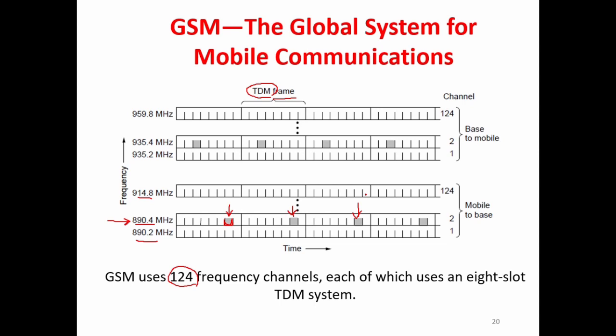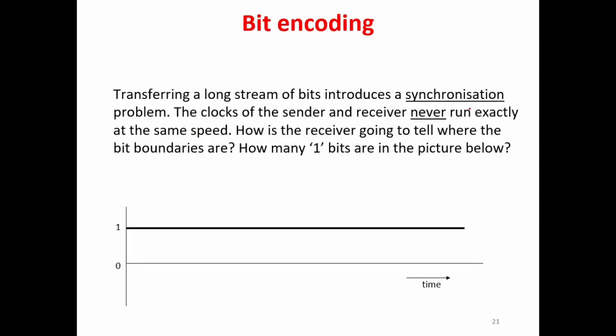But this happens actually in a very, very short time, so the receiver doesn't realize this is happening. So this sampling time would be very short. The procedure is like this. Here, for instance, again, automatically for this different time slot, the voice message is transferred from sender to receiver. And this is the application of TDM, working with time instead of frequency in the Global System for Mobile Communication.